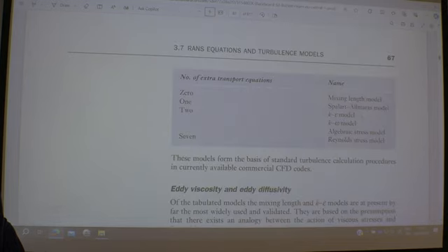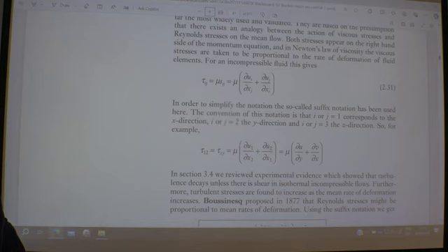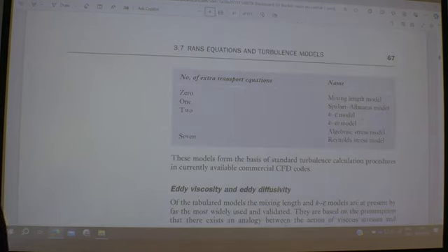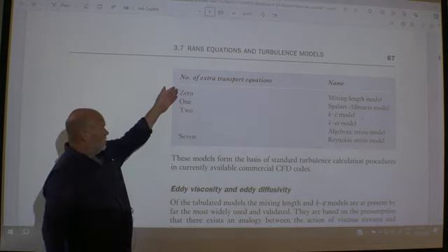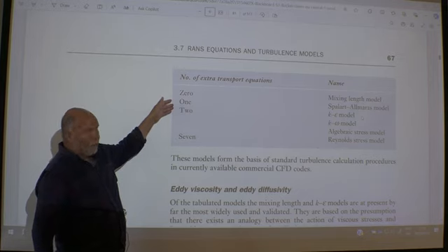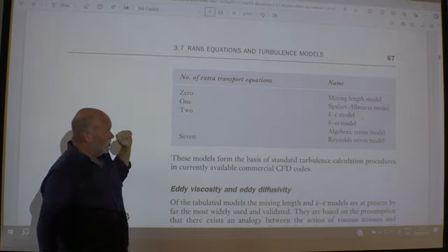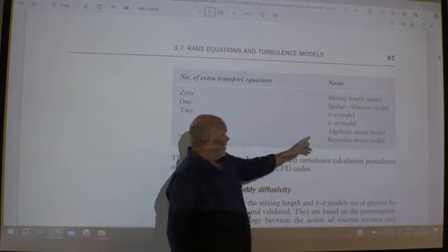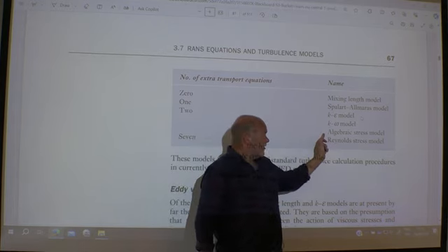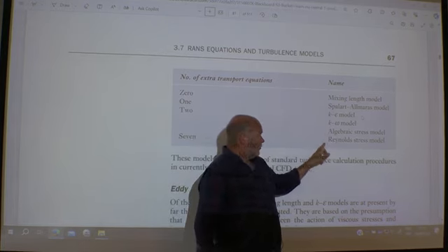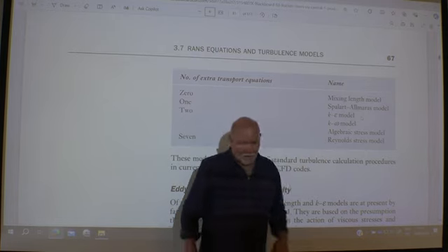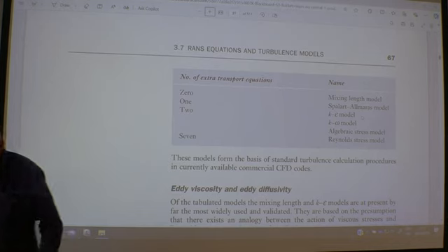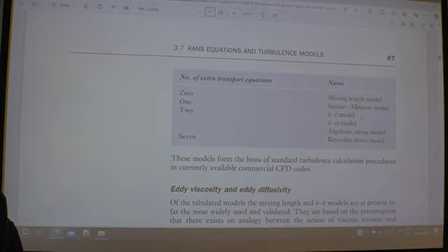So we will then use, say, the more classical equations. Not the zero-equation model, that's too simple. But Spalart-Allmaras, that's something you should know. Two-equation models, K-epsilon, K-omega. And then, as I told you about, this ASM model instead of a full Reynolds stress model. So the ASM, definitely something you should keep in mind.